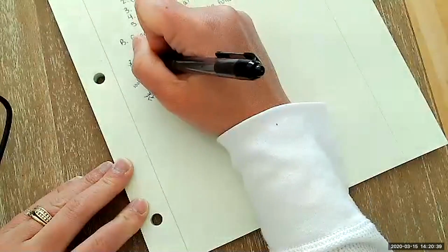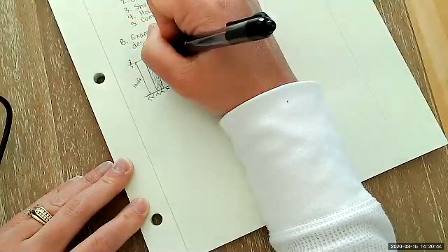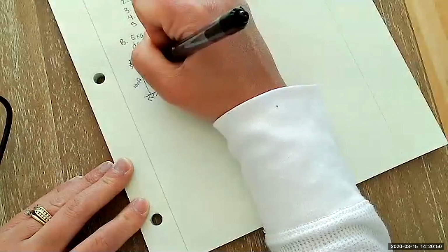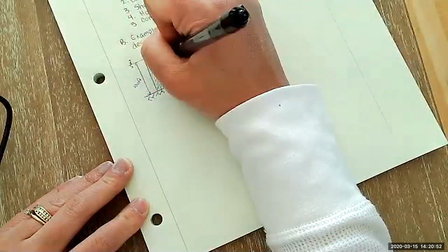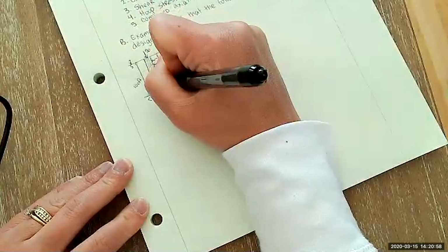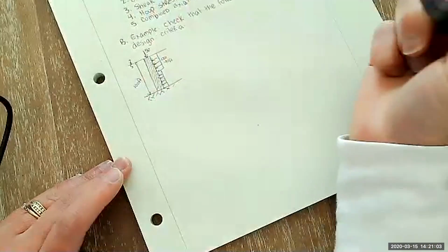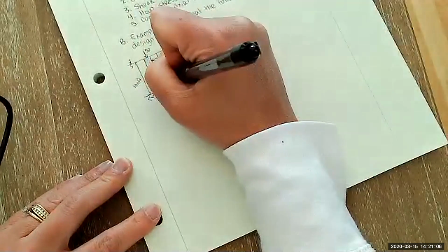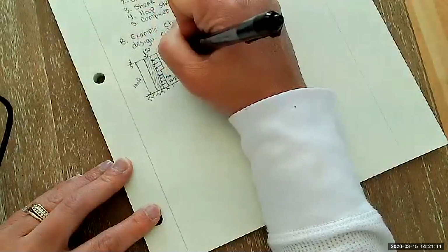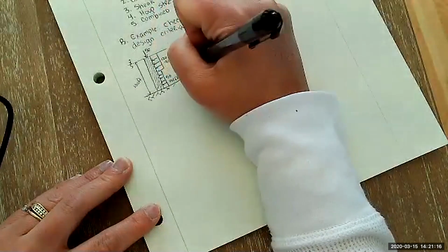And we have, so here's our column, a 120 pound per foot load acting along the shallowest 50 feet. So this is 120 pound per linear foot. And then as you move towards the bottom of the column, maybe you don't see as much load in this direction. So it's 50 pounds per foot. Again, the vertical extent of these loads is 50 feet and 50 feet.